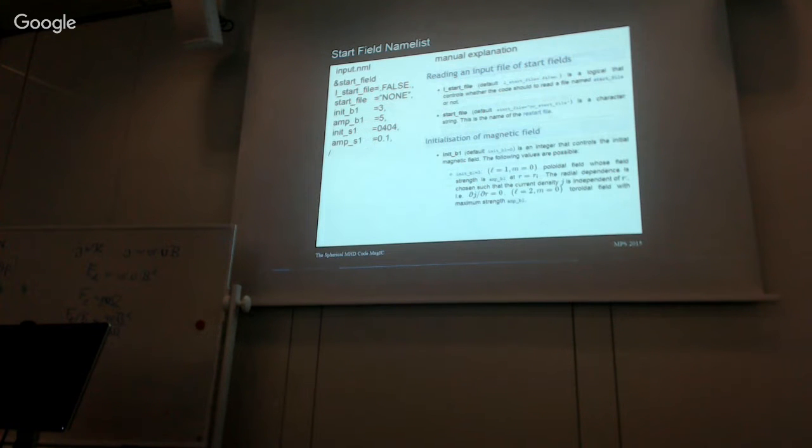Okay, now I also said we need a start field, a restart field. There are two ways, as I said, to define that. One is you read a restart file. So what you have to say is l_start_file. L stands for logical, equals true. Here it's false in this example. This is the next example you will use.